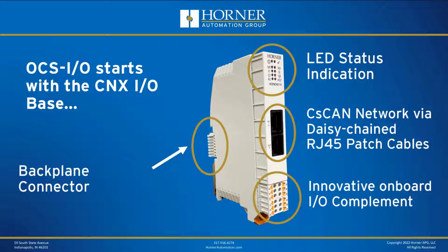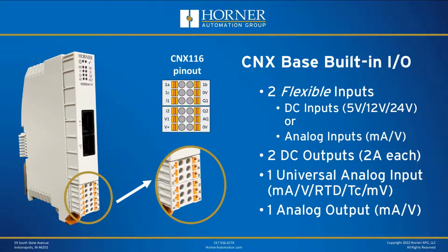Also, that backplane connector is pretty interesting, pretty neat. Basically, they snap together from side to side, yet when you install and uninstall modules, you can uninstall them from the middle or really at any point by just lifting the module straight off the DIN rail. So pretty interesting and pretty innovative backplane connector there from our mechanical package vendor. We talked about in the video the built-in I/O in the CNX base and the flexible inputs, those two inputs that you can use for either digital or analog.